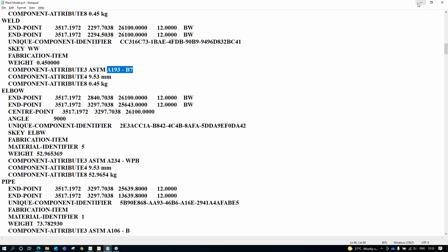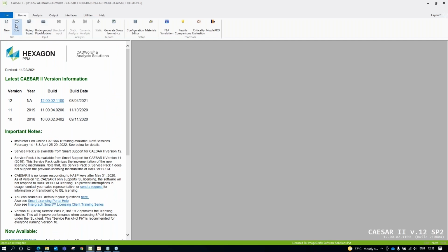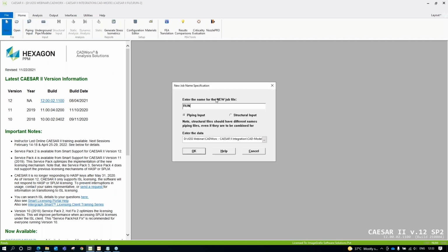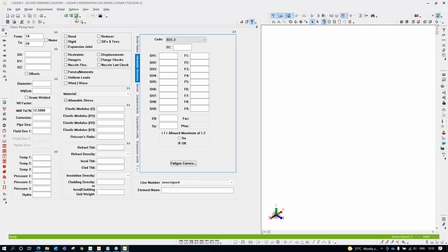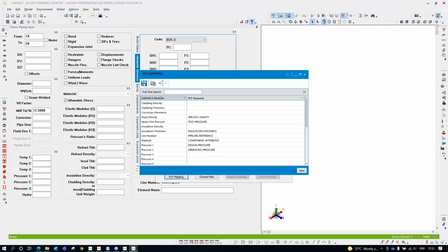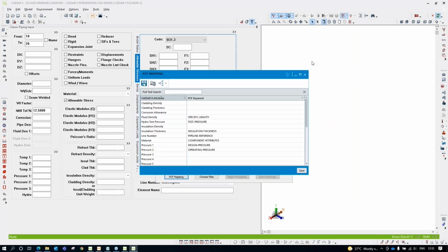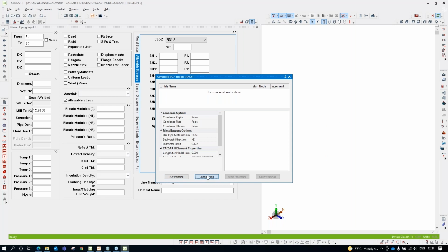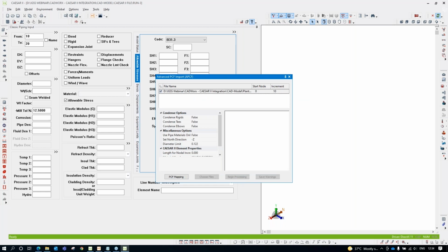Now let's do the mapping once again. Now we have mapped the materials. Let's rerun the file with the new material mappings. I'm just using the APCF because that has a few features which we can very much use, especially this kind of mappings and everything. Here you can go for this mapping. Same thing, you can open that mapping folder here also, so both are the same thing. Choose files, plant PCF, begin process.